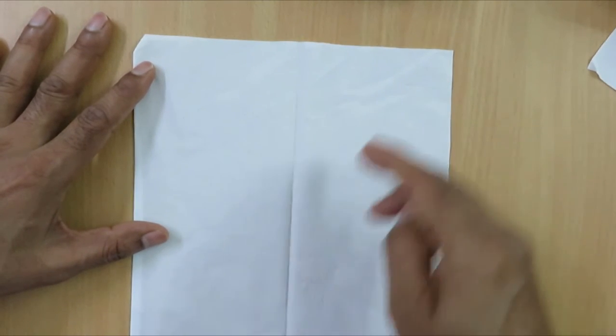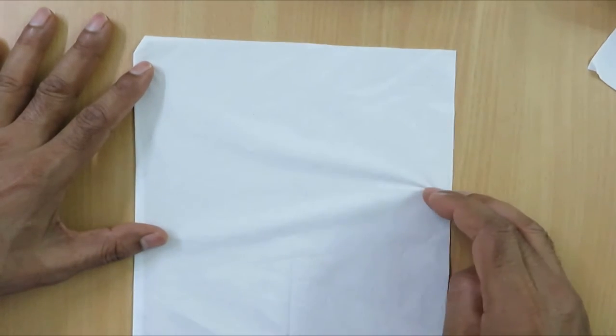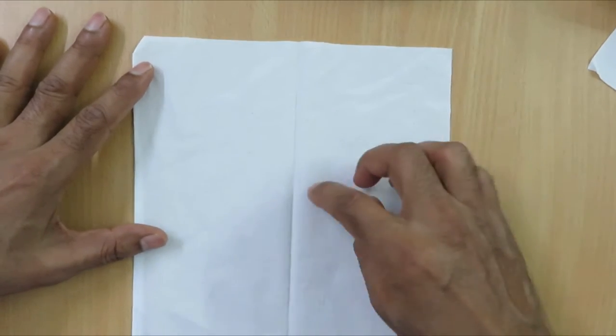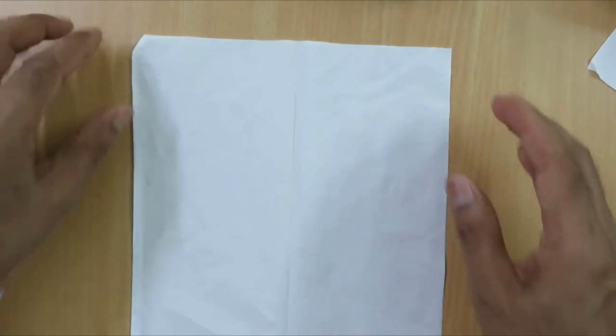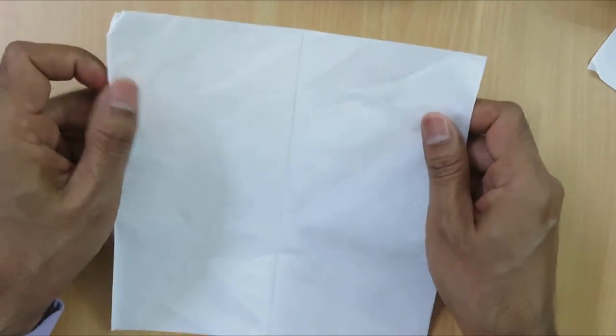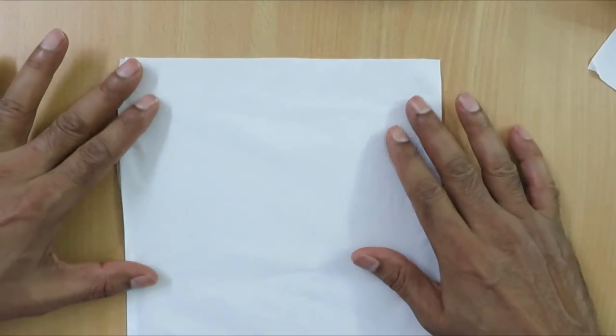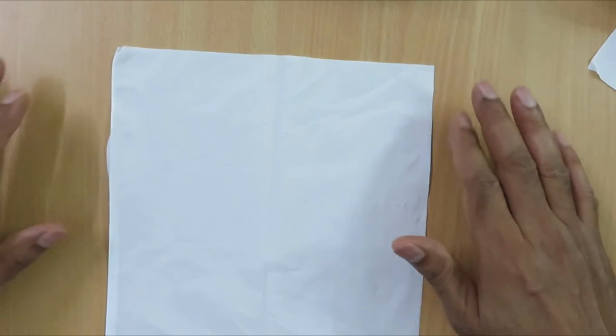So that means if we measure strength or modulus, both will be different in different directions. So as you change the direction, the material property will change slowly from very high value to very low value. In between you get medium values. So this is the concept of anisotropic material, and I have shown you this example of anisotropic material. This exists in many engineering materials as well as natural materials like wood. Wood is also very anisotropic.